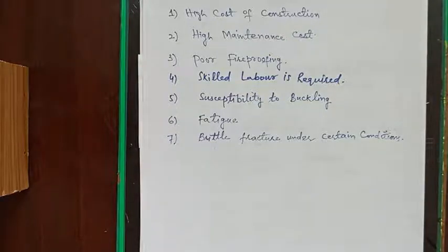Another disadvantage of steel is high maintenance cost. Exposure to water and air has a devastating effect on the steel structures because of corrosion. This requires painting of steel structures on periodic basis, resulting in high maintenance cost.